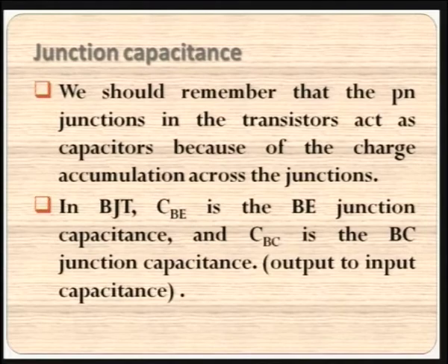In one of the earlier lectures, we came across this topic, how a PN junction could act as a capacitor. When we learnt about the diode, we discussed this point elaborately. We could even vary the capacitance value by changing the doping and by changing the reverse voltage across the PN junction. This has the application here.